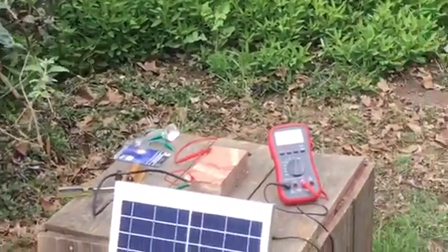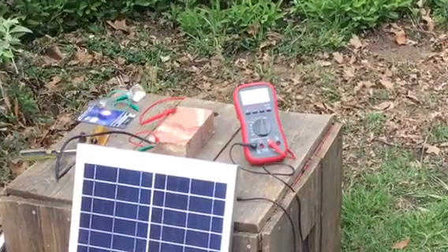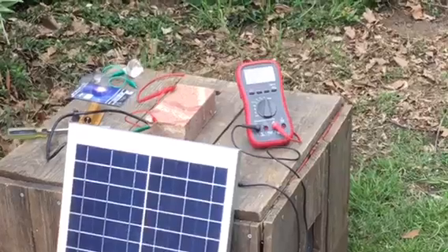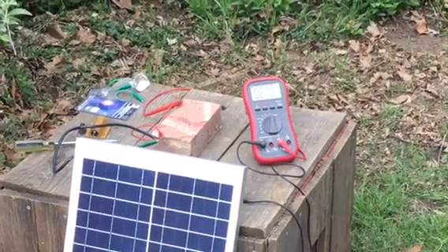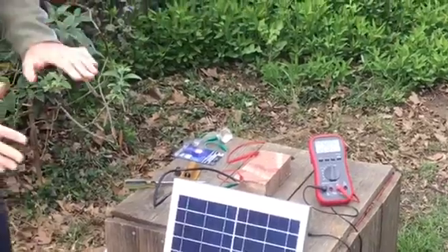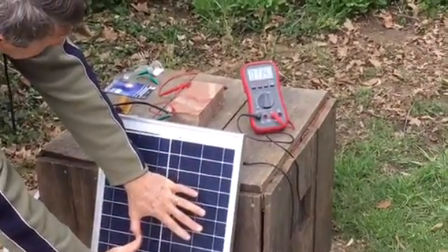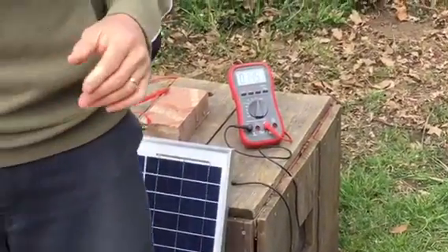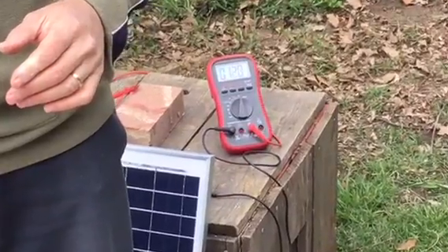Okay, not good. This thing should be able to produce pretty close to 2 amps, a bit under 2 amps, and it's doing about 0.28 amps. Okay, we can change that pretty easily. If I just go ahead and shade the collector a little bit, I'm getting less and less, and I'm just going to go ahead and stand in front of it and see if I can get it down pretty low. Okay, pretty low.